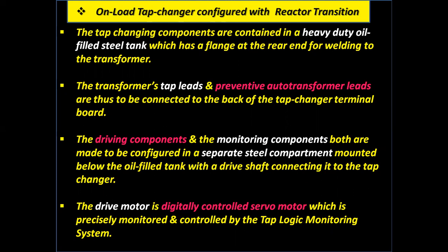changer terminal board. The driving component and the monitoring components both are configured in a separate steel compartment mounted below the oil-filled tank with a drive shaft connecting it to the tap changer. The drive motor is a digitally controlled servo motor which is precisely monitored and controlled by the tap logic monitoring system.